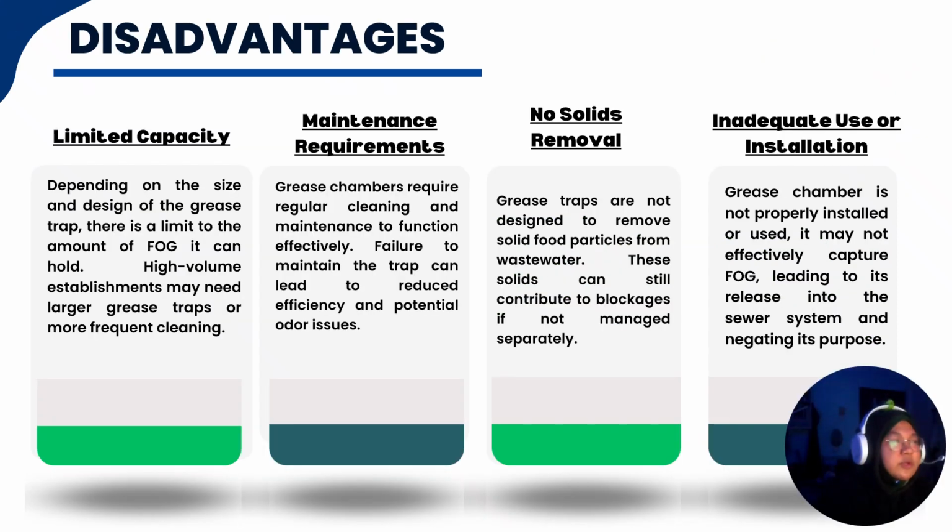Now let's move on to the disadvantages. First is the limited capacity. Depending on the size and design of the grease trap, there is a limited amount of FOG that it can hold. High volume establishments may need larger grease traps or frequent cleaning.